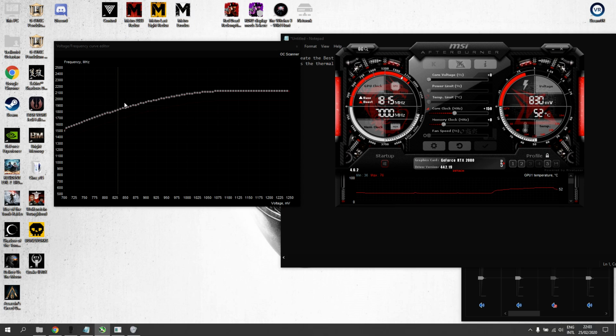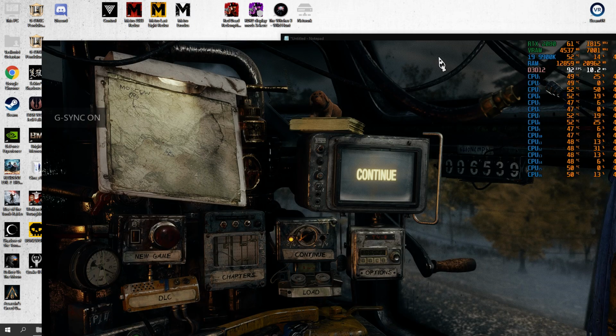So let's go and say, okay, what about this one? Not that one. Let's go about this one. Oh, let's go at 1950. I want 1950. I like 1950, right? But that's 0.9 volts. Well, let's try it. 0.9 volts. So, wow, that's an overclock over the reference spec of 215 megahertz and 135 over the Founders Edition. Awesome. Let's see.